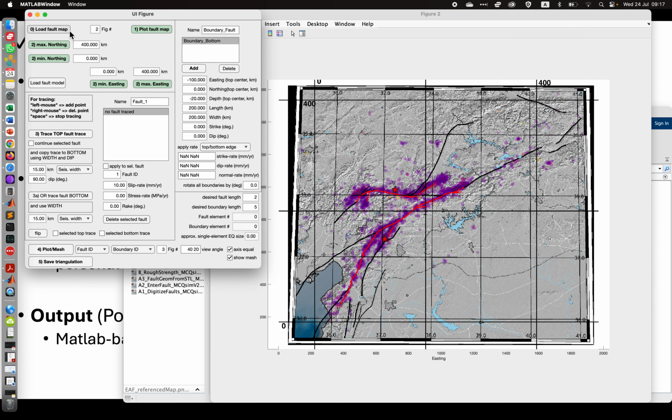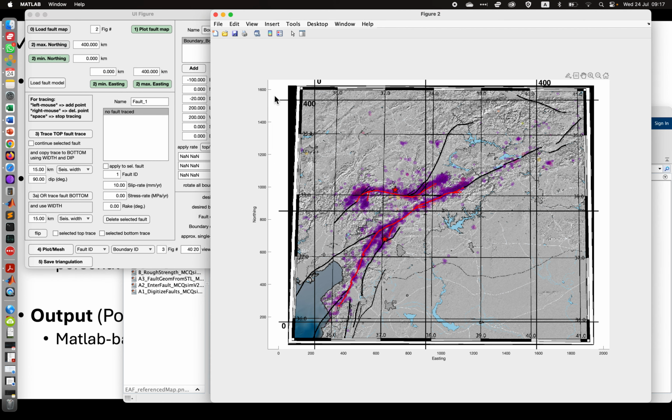So the way this works now is that I have defined what the maximum northing is, so this higher value for the northing, and I can then click on this button, which allows me to use the G input and then specify at which, in this way, top down or up position this maximum northing is, and I can see it here in this line, so I will click it here. Since this is only for northing, only for the referencing part, only the up down component, let's say the Y component of this coordinate is actually used. I just pressed the mouse button once and this value is now fixed.